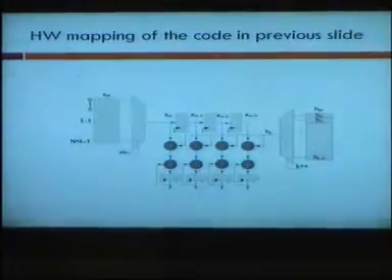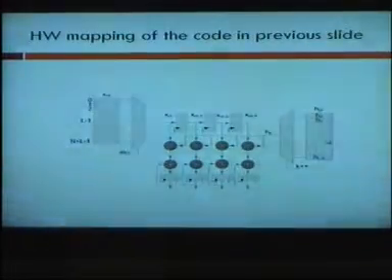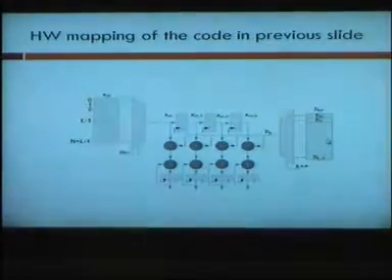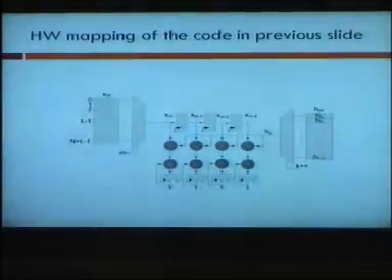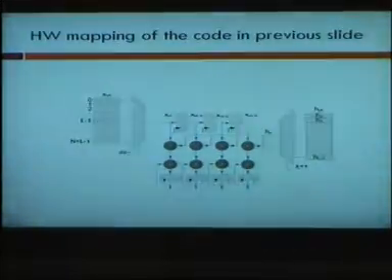Then H you just put in a ROM, meaning all the constants, and then it's up to you how many multipliers. This is the beauty of hardware: whether you want 1 multiplication addition, 2, 3, or 4 multiplication additions, it's all in your hand.